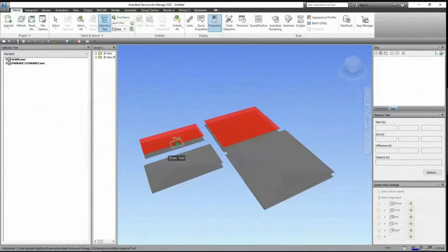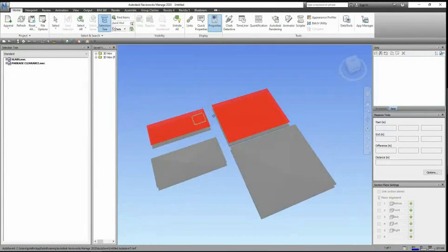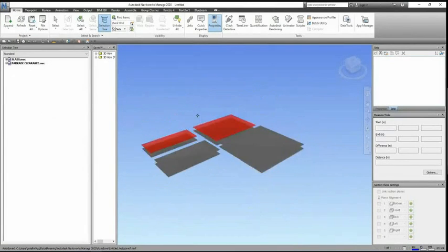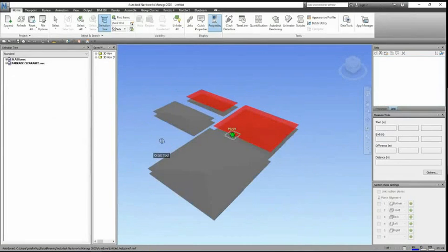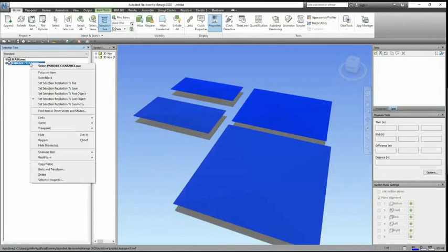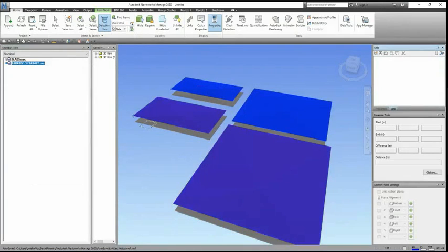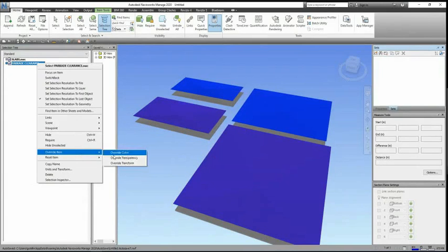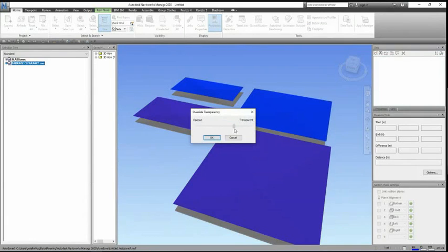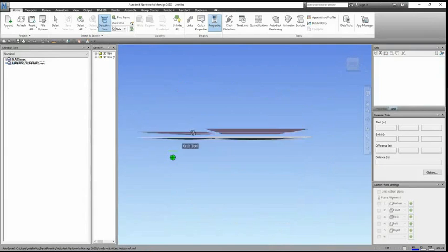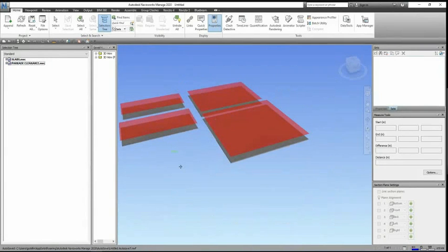So there's the slabs. Now, there's a few ways you can preset the visibility through materials if you want in Navisworks. I honestly haven't quite gotten that figured out. So what I actually do, just as an easy workaround, is just simply set the visibility settings in my NWF. The reason I mention it's sometimes better to do this in Revit is so that you can just skip this step. So whenever you do update your NWC, you don't have to remember to do the additional step of changing the visibility and putting a transparency on that parkade clearance, because that's the thing that you want to do, is make sure that it's a color that's very noticeable. In my opinion, I like to do that. And then set it to a transparency that's either half or maybe 60% transparent, so that you can kind of see through it, but any surfaces that poke below it, they will be clearly visible.